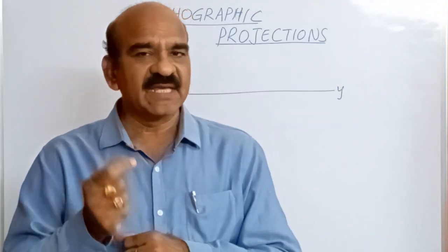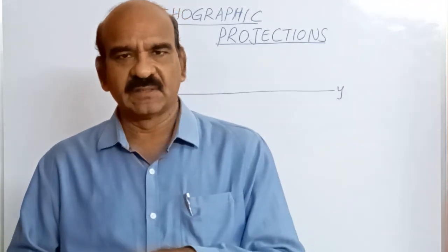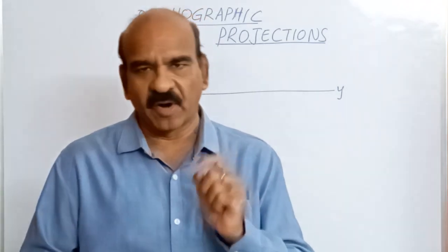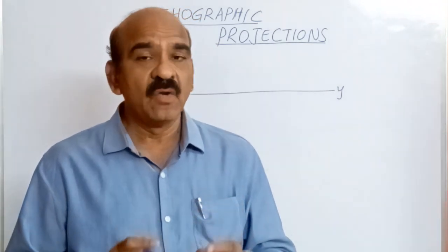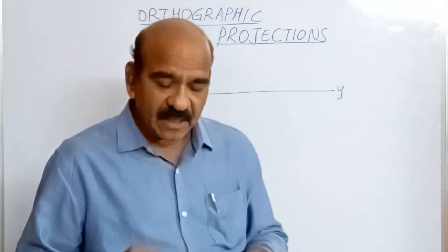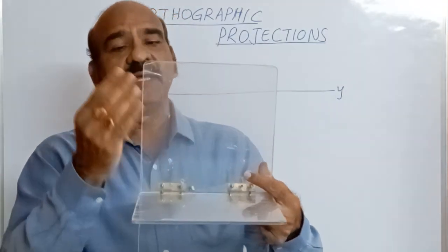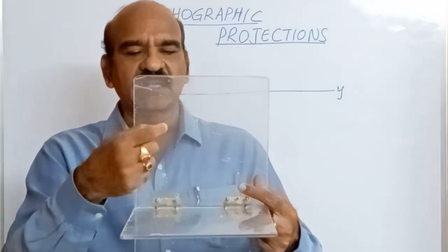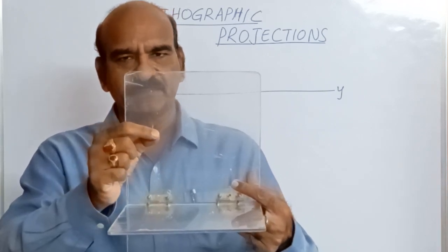Before we start with a single one-dimensional line, let us start with a no-dimensional object. That is nothing but a point. So let us see the projections of points. Suppose I take a point A. We have to specify where that point is. Suppose the point is here. It is said to be in the first quadrant, in front of VP, above HP. Okay? Now the point is 30 mm in front of VP, 40 mm above HP. This is the position of the point.